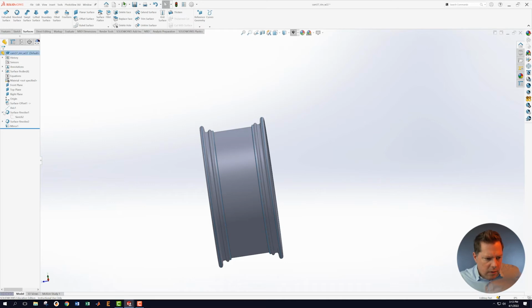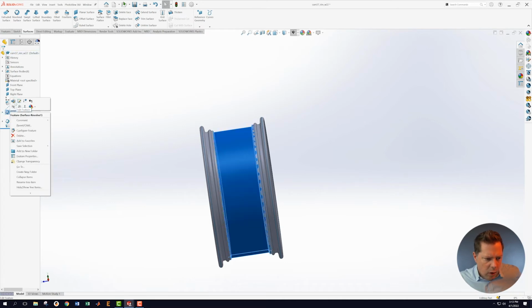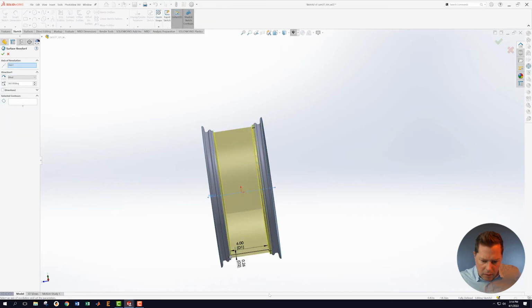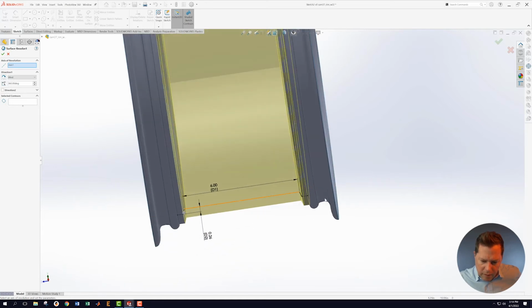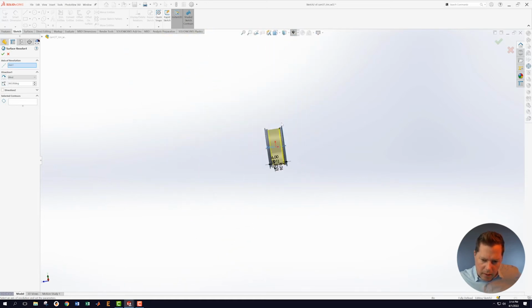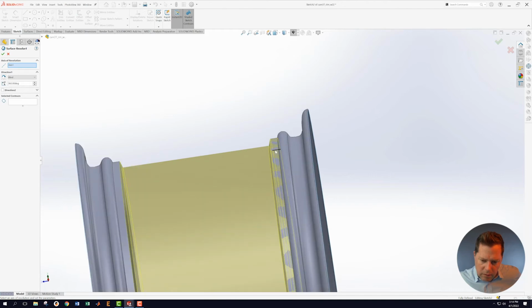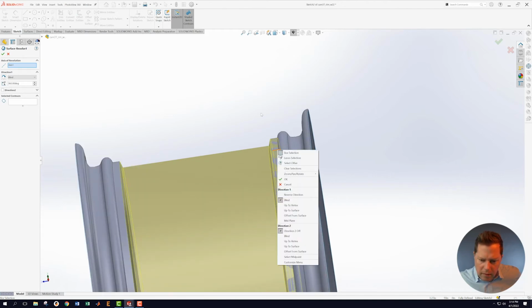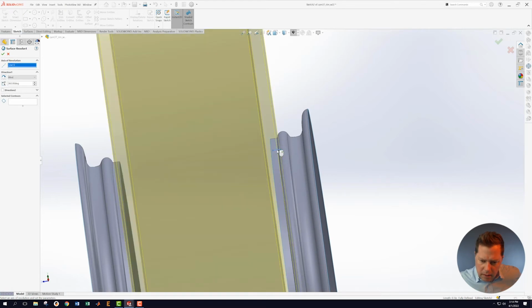So I'm going to go back into this revolve. I'm going to open this revolve, edit this feature. Okay, here's the problem. I've got this thing right over here, down at the bottom, that's revolving around, while at the same time I have this thing right here revolving around, which is probably the reason why we're having this mistake. Let's try to delete that. Can I do that?